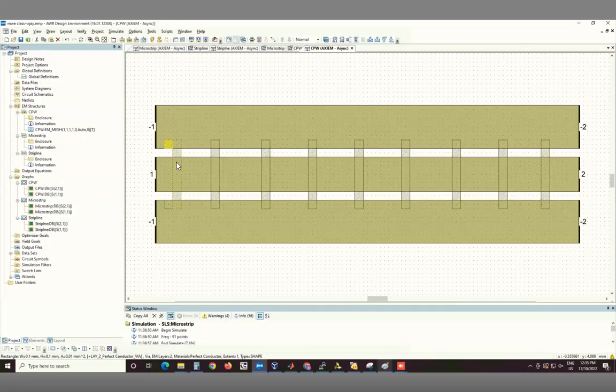So for whatever the relevant frequency of operation is, you have to think about the wavelength and then put these at distances which are maybe a tenth of a wavelength or so. That way you know that things cannot change so much from this point to this point. But you are right that the ideal thing would be that it's continuously stitched, but that's not practical when you are making these things. You can't have that many vias. That's why you do it as much as possible.